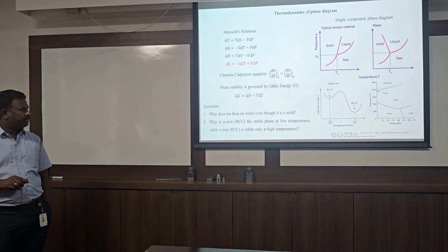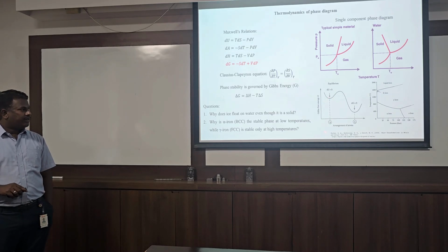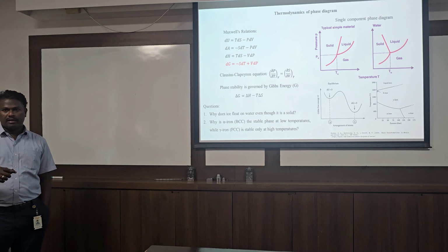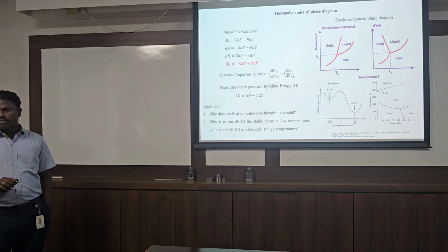So what is the equilibrium? Suppose free energy versus different atomic arrangements. I see that this B type of configuration has a higher energy than A type. So within these two arrangements, A is the most stable, and you can say it is the equilibrium. Equilibrium means whichever has the minimum possible, lowest Gibbs free energy. That is our equilibrium, we say.